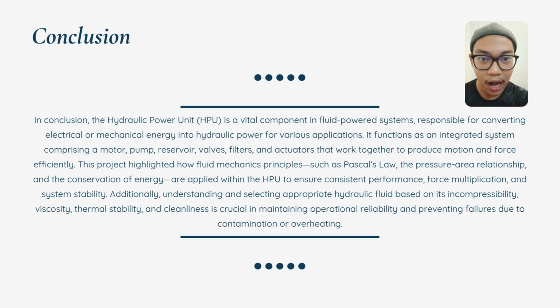This project highlighted how fluid mechanics principles such as Pascal's law, the pressure-area relationship, and the conservation of energy are applied within the HPU to ensure consistent performance, force multiplication, and system stability. Additionally, understanding and selecting appropriate hydraulic fluid based on its incompressibility, viscosity, thermal stability, and cleanliness is crucial in maintaining operational reliability and preventing failures due to contamination or overheating.